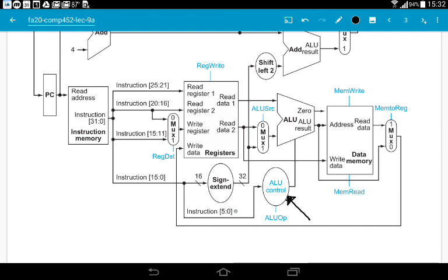Look, these 6 bits are the function code. They come from the least significant 6 bits of the instruction, bits 0 to 5. They are going to the input of the ALU controller, and these are actually 2 lines, which will be coming from the main controller. And this is the output of the ALU controller, going to the 4 inputs of the main ALU.